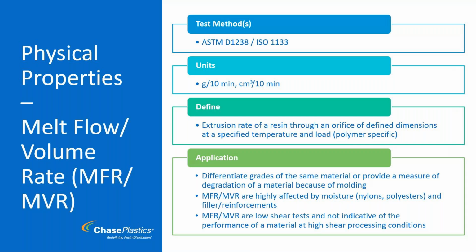Same as comparing a 20 melt PC to maybe a high flow lens grade of PC that's at a 65 melt. I know that the 65 melt will flow dramatically more than the 20 melt. It won't be the exact 3-ish times amount when it's under the shear of injection molding, but I do know that it will flow a lot easier.